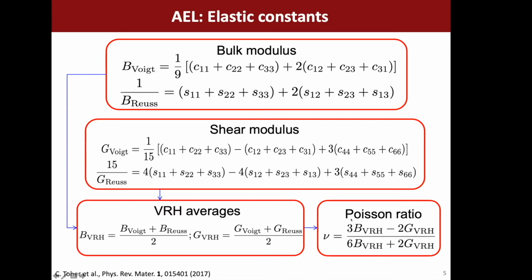From this, we can calculate other elastic and mechanical properties, things like the Poisson ratio. You can also estimate the hardness based on a combination of the bulk and shear modulus, although this tends to be better for nano hardness, and tends to work better for ceramics than for metals. In metals you have things like slip planes that strongly affect the behavior of the materials.